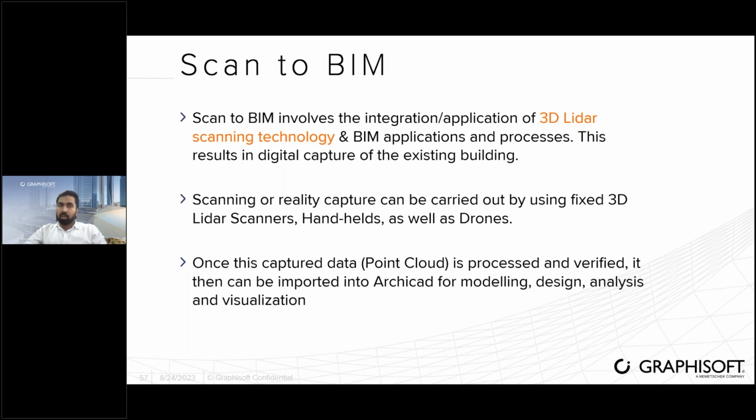Or even when you want to compare the as-built model with the real construction, you can just do a scanning. It can be either using handheld scanners or even using drones. Once you scan that, you can import the point cloud data in XYZ file format inside Archicad, using which you can compare it with the as-built model. So in both cases, this workflow is quite helpful.